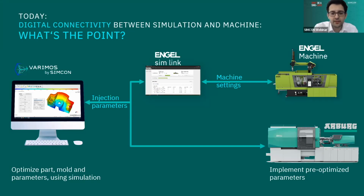With ARBURG, there's a direct connection to the machine via the ARBURG Fill Assist module. It's on the machine itself and translates the machine injection parameters to pre-optimized parameters on the machine. This is currently only available on Gestica systems. So only if you have the newest Gestica control on the ARBURG machine, then you can use the ARBURG Fill Assist and have this connection readily available.